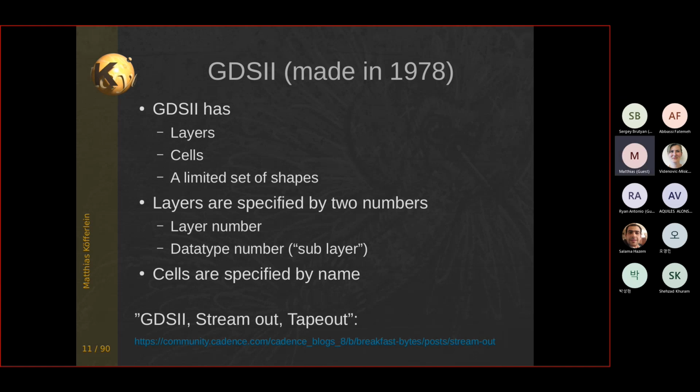So what we do here is basically we're working directly with GDS. In Virtuoso, you work on an intermediate database, which is typically OpenAccess today. In KLayout, you directly work with GDS. So there's no stream out in that sense. You just give your layout file to the mask maker, if you're sure it is done properly or verified it.